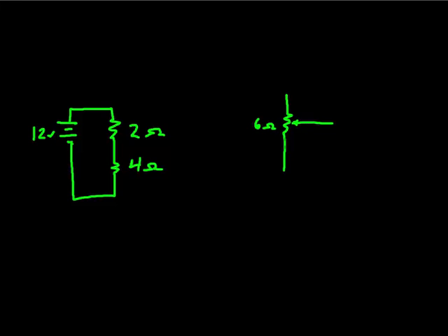All right. So if you remember the schematic symbol right here that we used in the last video, it is the schematic symbol for a variable resistor. It may also be drawn like this with an arrow through it, but more often than not, you actually see an arrow drawn straight into the resistor like that. And what it implies is basically the same thing as this, right? So if you had this, remember a potentiometer has 3 nodes to it, right? So if you measured the resistance between here and here, and the wiper was partially down this resistor, you may be sitting with 2 ohms of resistance up here, and if you measured from this point to this point, you would measure 4 ohms.